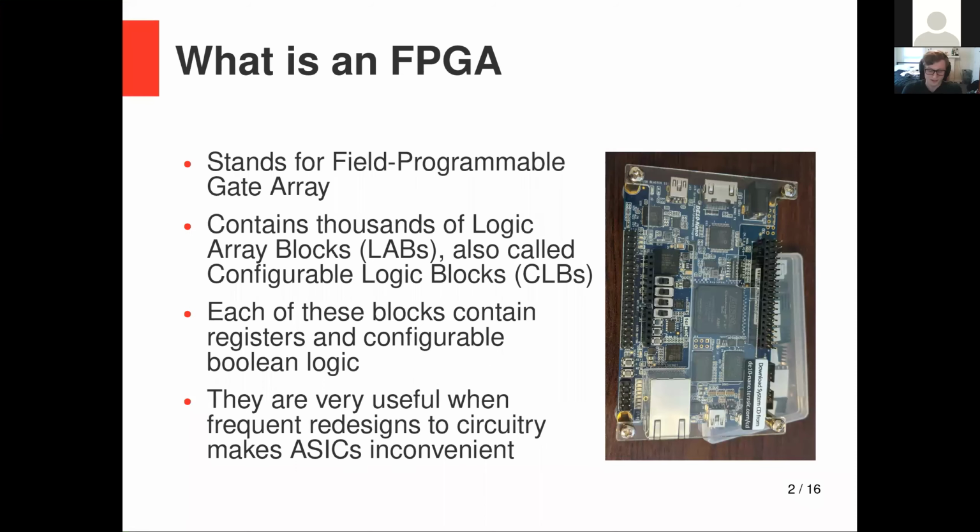There we go. So, as Nathan was saying, what is an FPGA? Well, it stands for Field Programmable Gate Array. Basically, these are chips that contain thousands of logic array blocks, also called labs. They're also called configurable logic blocks, depending on which manufacturer you're buying from, because they like to use confusing different language. Each of these blocks contains registers and configurable Boolean logic, and they are very useful when frequent redesigns to circuitry need to happen,